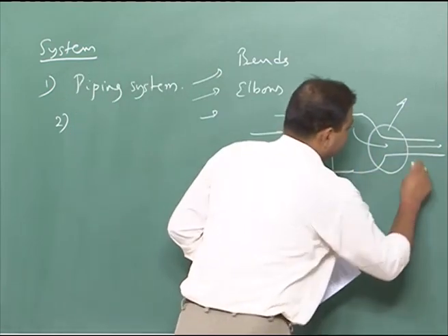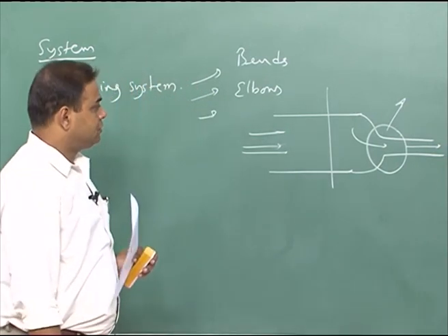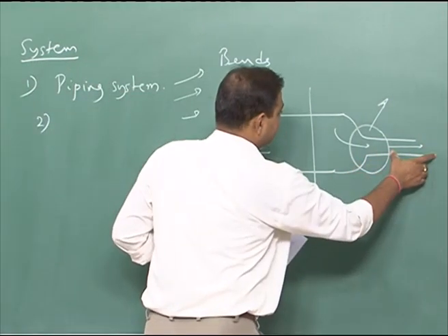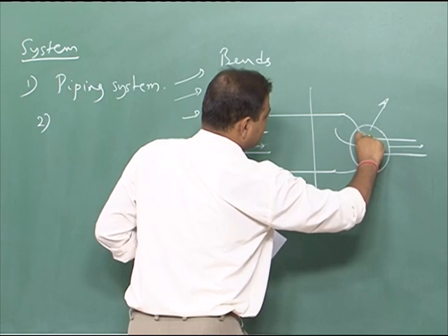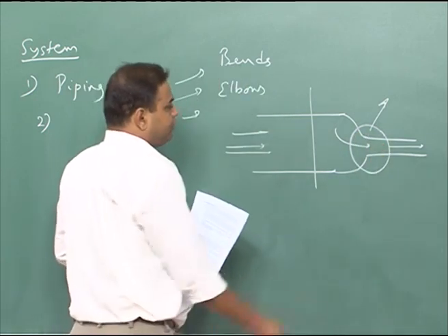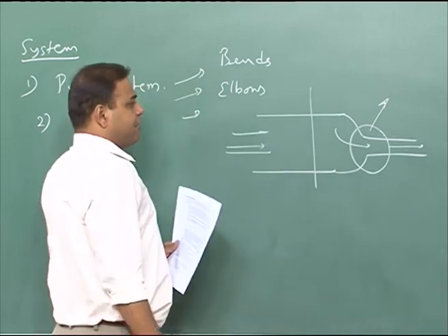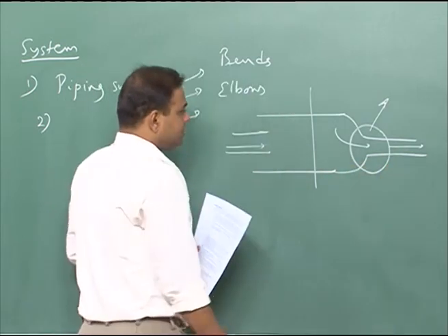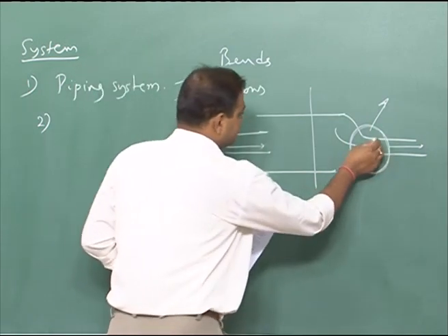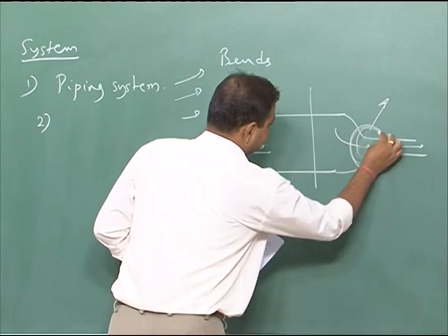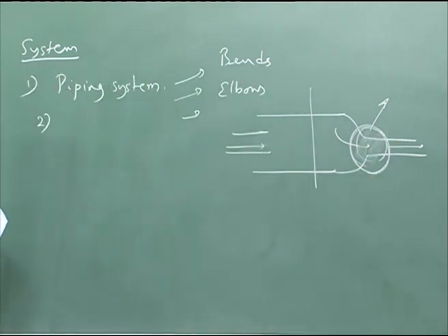Only after a short distance does the solution assume laminar flow again, but till that point there will be a lot of turbulence, and due to that effect the corrosion would be more in this section. So, this is another system or situation where we can experience erosion corrosion.